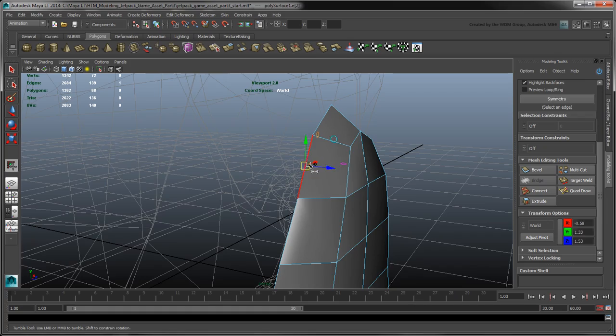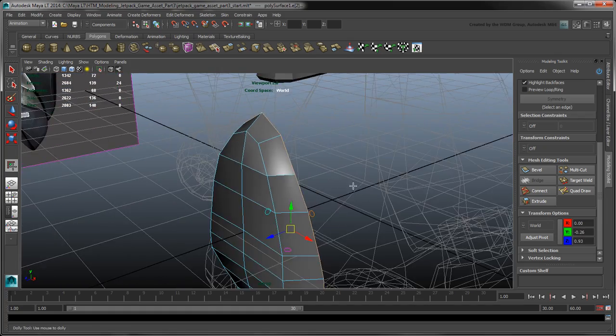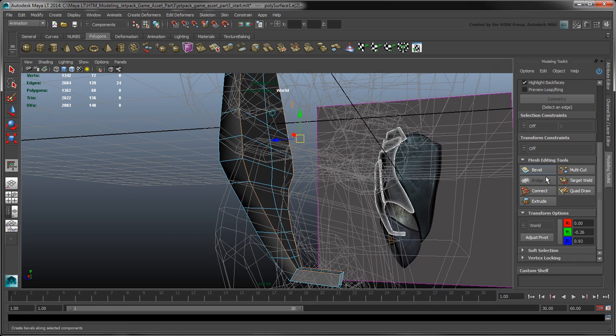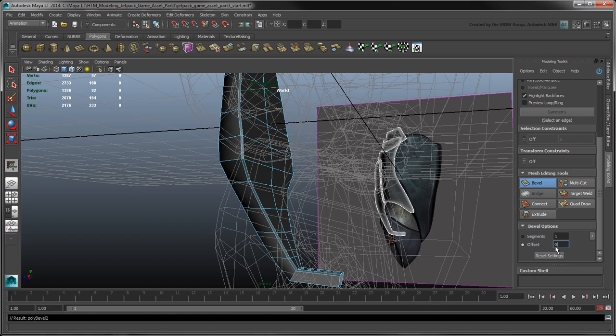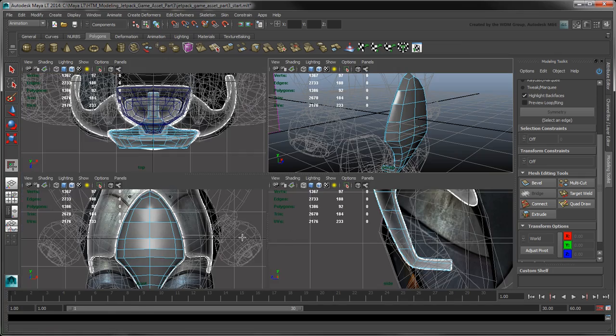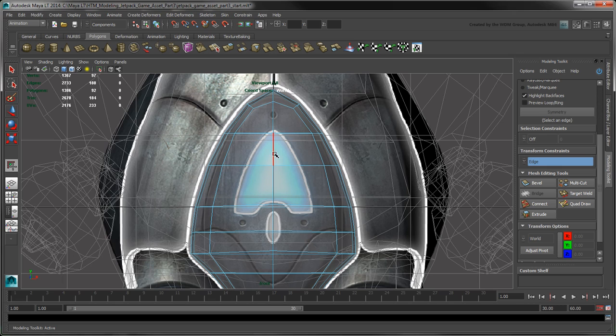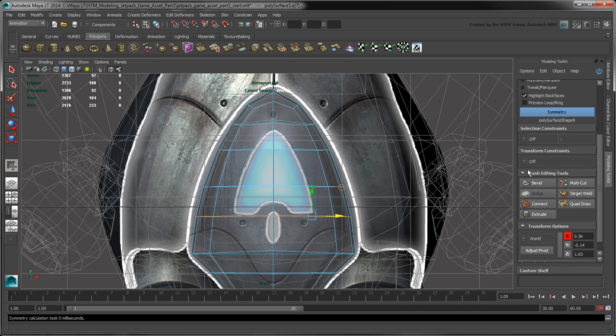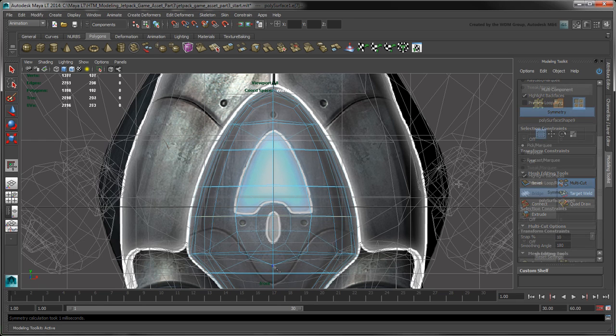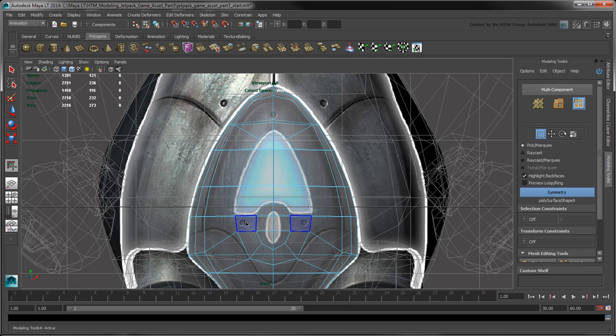Select the border edge loop and bevel it. Set offset to 0.5. Using the techniques we've seen so far, create the remaining cavity in the middle of the panel. Remember to keep a clean topology so that you can make these quick alterations to your mesh.